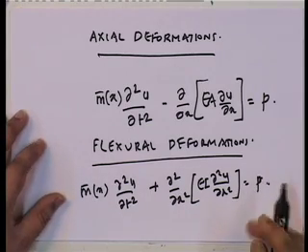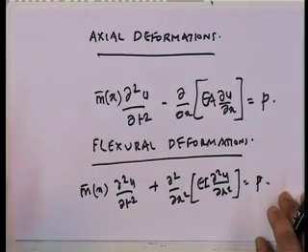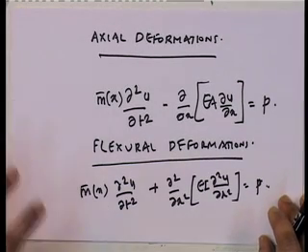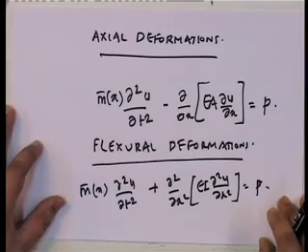The reason why I am calling it a simple beam is that only flexural deformations are considered and only linear inertia is concerned. Later on in this course, towards the end, I am going to be talking about what we call a Timoshenko beam. In a Timoshenko beam, not only do you consider flexural deformations, you also consider shear deformations, and in addition to the linear inertia, you also take rotatory inertia of a beam. That's known as the Timoshenko beam.